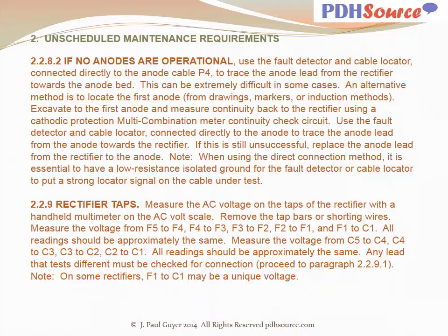Note that when using the direct connection method, it is essential to have a low resistance isolated ground for the fault detector or cable locator to put a strong locator signal on the cable under test.